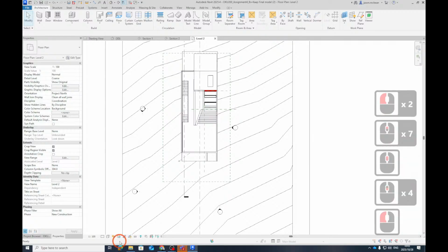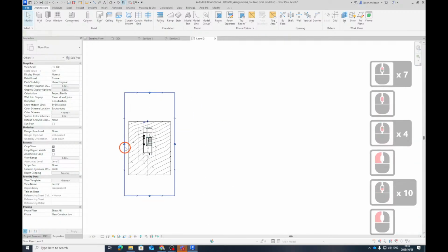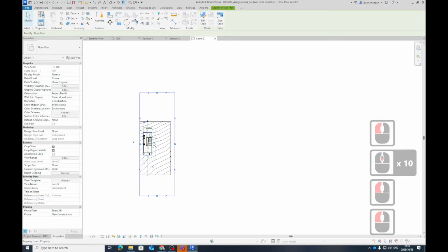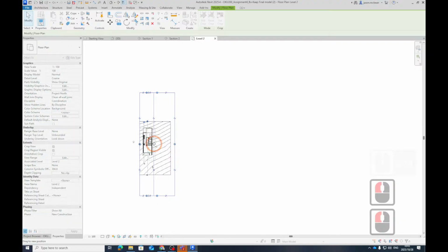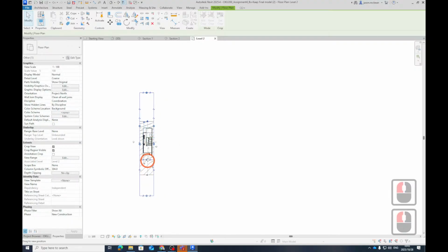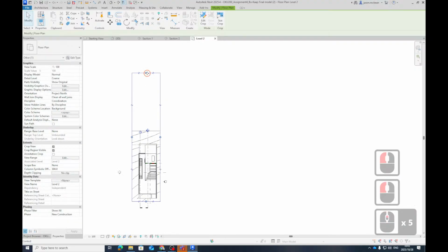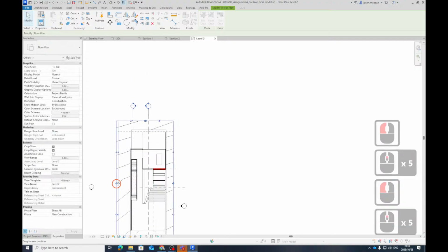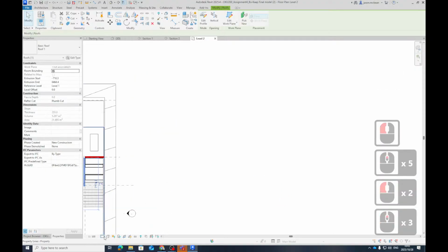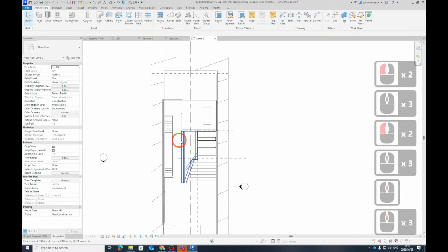And just remember with Revit, you've always got to crop your views, because when you put this on your sheet, Revit wants to know exactly what you need to see on your sheet. So make sure that you crop. Very important. In my annotation videos that I've given you guys, I've explained this quite clearly. Make sure this is all you're looking at, and make sure it's always fine. Construction will always work with fine detail.